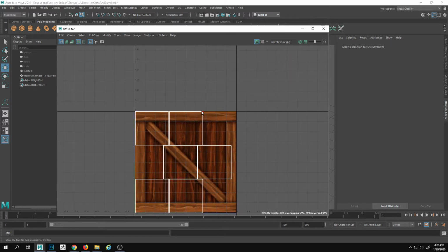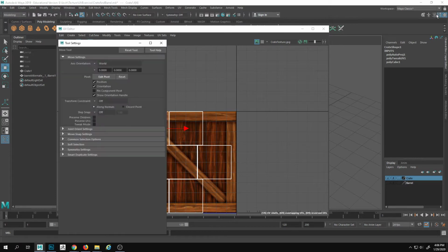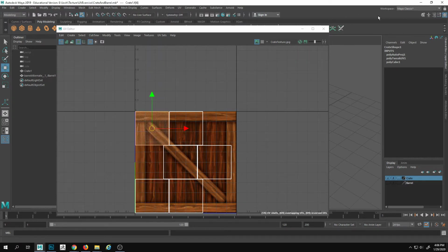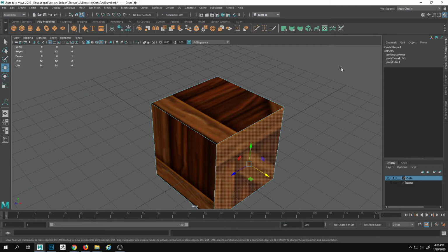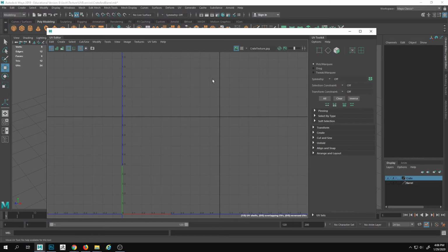Okay. First thing that we should be aware of. My viewport for the controls here seem to have disappeared. If that ever happens, if Maya starts to give you problems, first thing to try is Maya Classic, Reset Current Workspace. Now it might make a menu disappear on you, but what that's going to do is try and break anything weird that might be happening and bring it back.